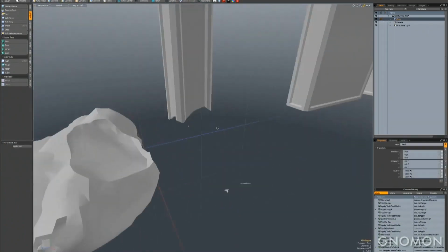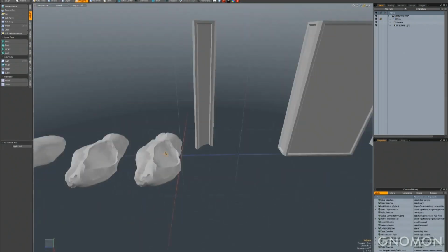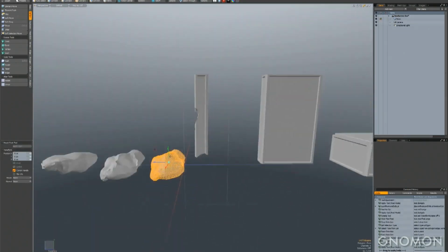So right here, we'll just go ahead and start cutting the stuff out of the mesh. And this is the way that we did a lot of the pillars in those Doom screenshots that I showed earlier, is we just take the stuff and just start Booleaning stuff out.